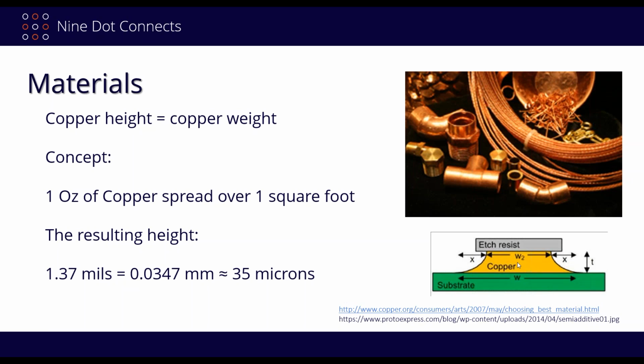Unfortunately, there's never a perfect trace, though. I'm seeing some stuff from companies like eSurfaces where, with the additive measures, it's amazing how square those traces look. But for the most part, what we're doing is a subtractive process. It's a little bit of give and take. You just have to understand the chemistry behind it. It's not going to be perfect, and so you're not going to get a perfect square. In fact, you're not even sure what you're going to get.